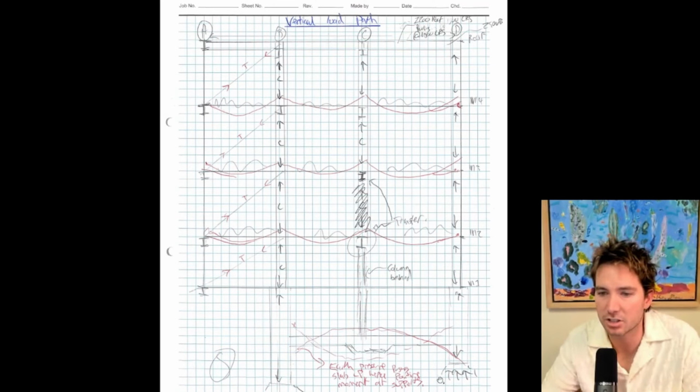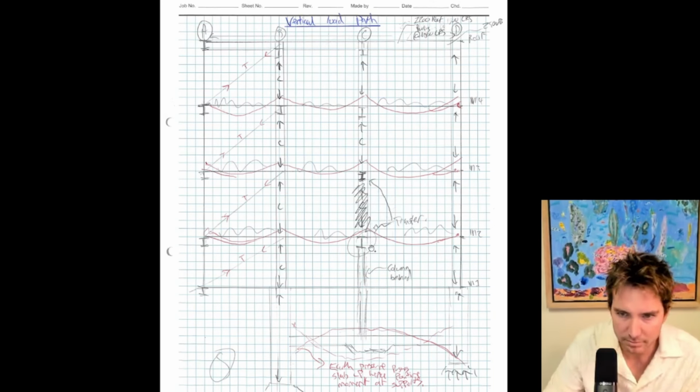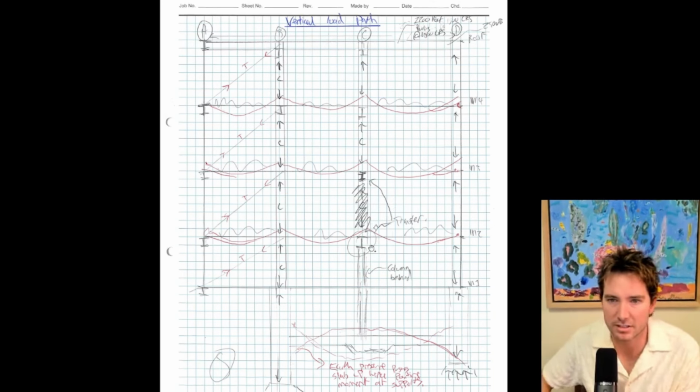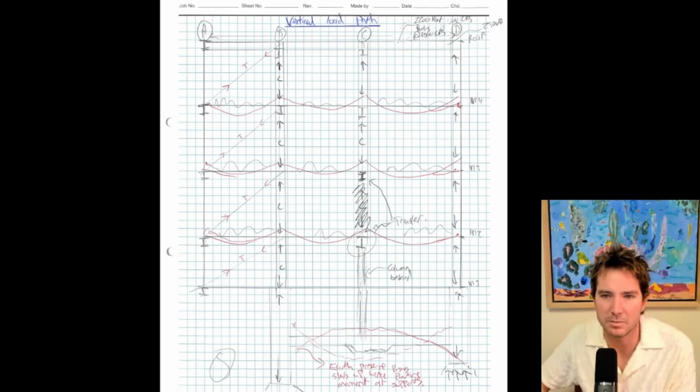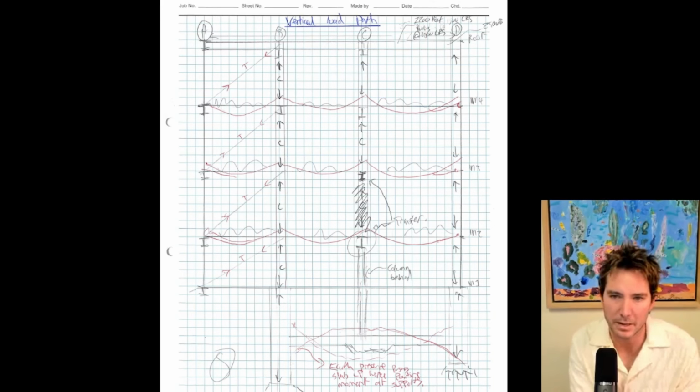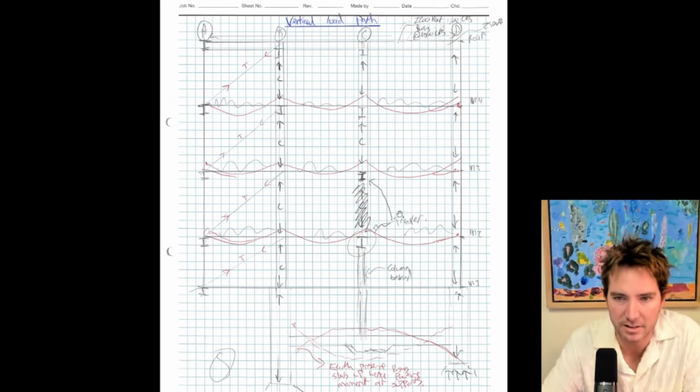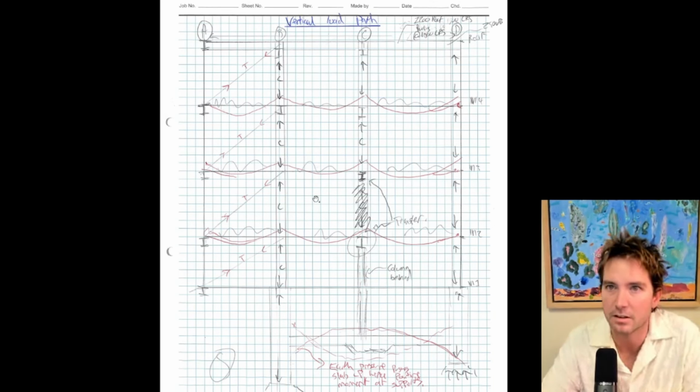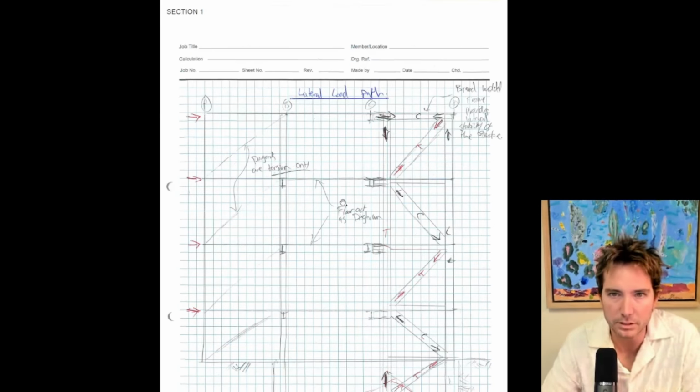And again, I'm just sketching that the D walls aren't loading that existing sewer. My diagonals are picking up here. I made a mistake with the transfer here. I kind of forgot where it was. So this is just, I guess, the benefit of doing something practice live. I didn't have time to sketch everything up. I think I possibly also used pen to begin with, as you can see there, so maybe it's another benefit of pencil. But I just scribbled out and pointed, my transfer's up here. Understand that. So my lateral load path.